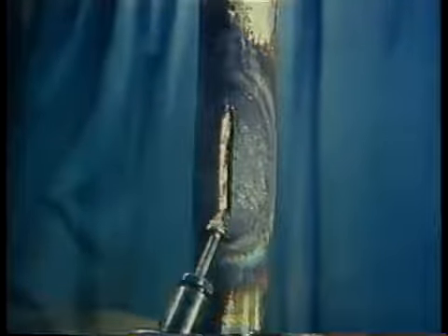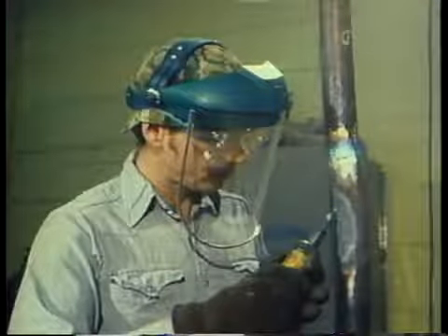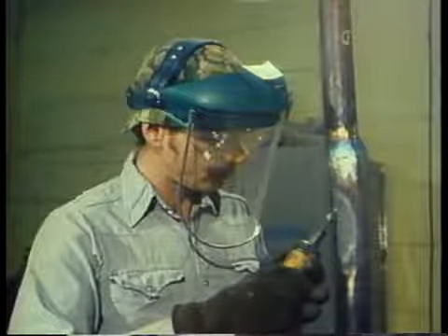Once the edges are as close as possible, they're prepared for welding by grinding them smooth. A V is made in the opening at a 35 to 40 degree angle. Whenever you're near a grinding operation, wear face protection. Ear protection may also be required. The full length of the opening should be ground, paying particular attention to the ends. The tapered ends should be ground so that they are rounded. This is important because the tube can rupture in the exact same place unless the ends are completely ground.